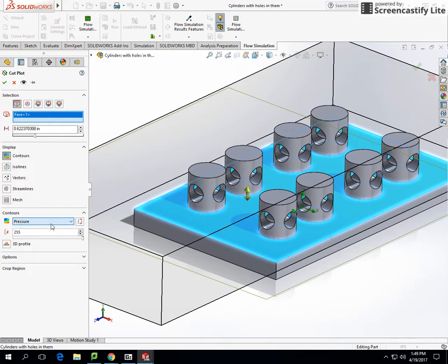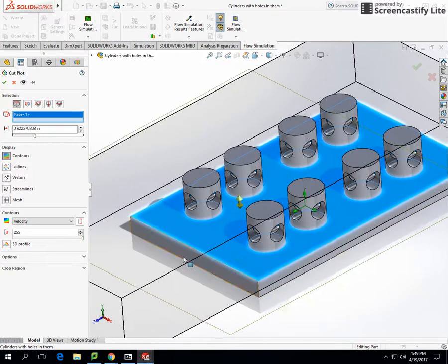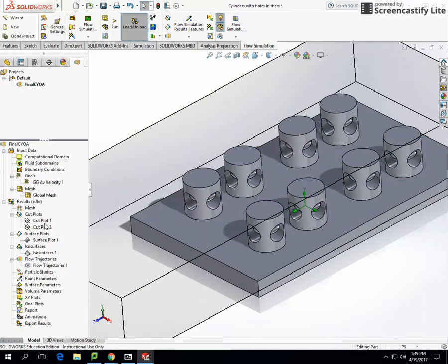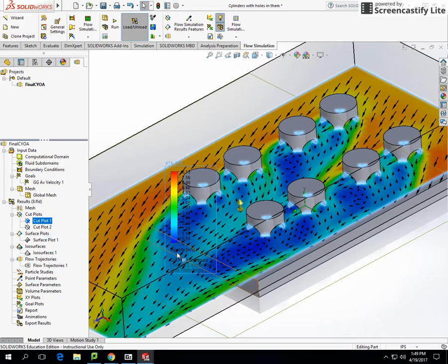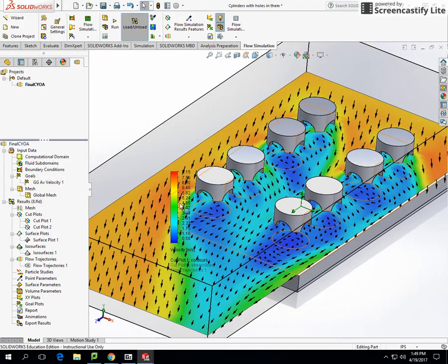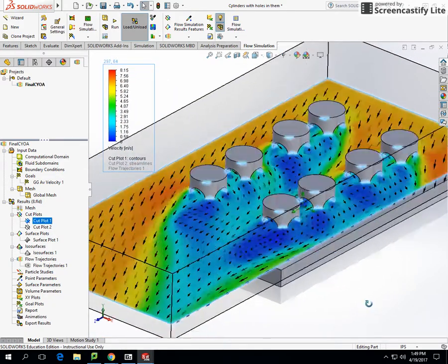And then just make sure down here that you have the correct option selected, and then you can change the number of levels. So a higher number will give you a smoother, more chromatic graph. So once you do that, you can hit OK. I've already got one made up that I'll just show you. And then you can drag and drop the scale bar there.